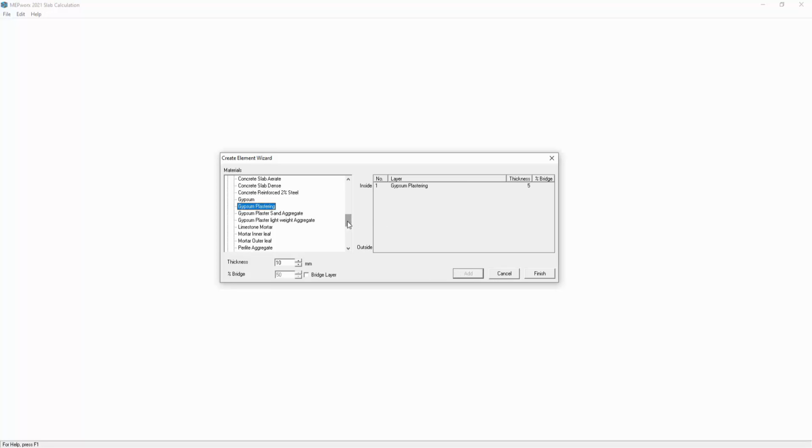You then move on to the next material. So the next material might be some blockwork or plasterboard. So we can move to the next category, put the plasterboard in there, and let's say it's 15mm fire line, so 15mm, select the material of interest, add that in. Wall linings, plasterboards, close that down. Next up we might have some internal blockwork, so we can go for the blockwork category, selecting the blockwork we want. We've got a whole range of blockwork in here, putting the thickness of the blockwork in, selecting the blockwork itself, adding the blockwork in.